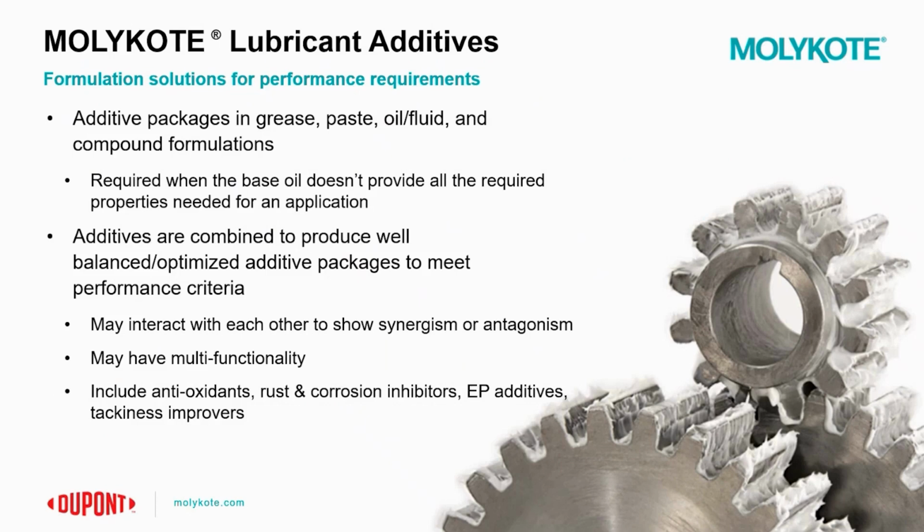Next we could take a look at lubricant additives, which are incorporated into formulations. Additives are incorporated into specialty lubricant formulations when the base oil itself doesn't provide all the required properties needed in a given application. For example, if an application requires fretting resistance, it's unlikely that a base oil alone would provide all the functional benefits needed in that application. So additives are incorporated into the formulation in order to meet performance criteria.